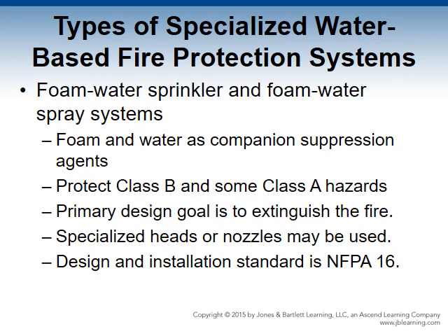The equipment-related differences include the incorporation of proportioning equipment to make, obviously, the foam with foam concentrate. In some instances, the use of specialized foam water sprinkler heads or spray nozzles can be present. In order to look at the design installation standards, you must reference NFPA 16, which covers all our pertinent information from inspections, testing, and maintenance. And there can be some additional requirements that are covered in NFPA 30 and NFPA 409.